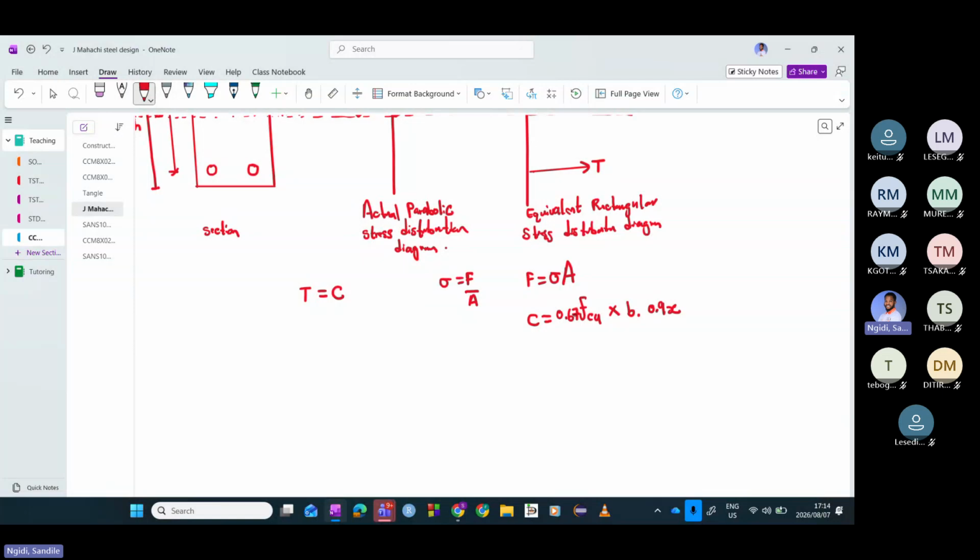this factor of 0.67, the reason we are multiplying this stress with this factor is that, remember, this 28-day compressive strength of concrete, we get it from crushing concrete, and this happens in the lab. But then we use this concrete on site, and there might be differences between the strength that we test in the lab and the strength that we'll have on site.